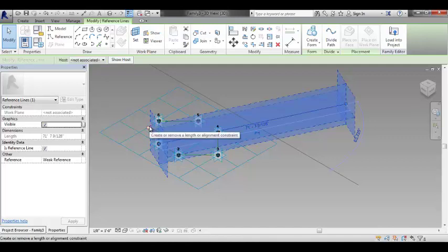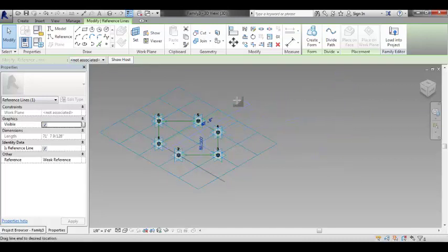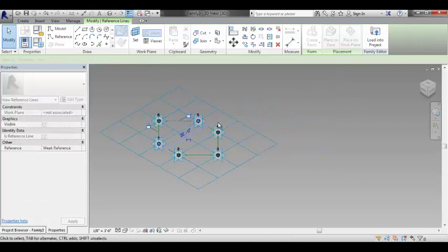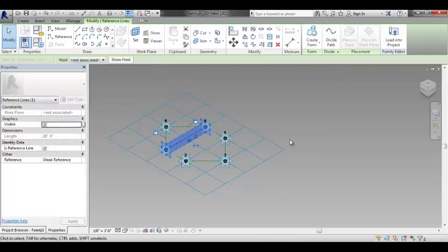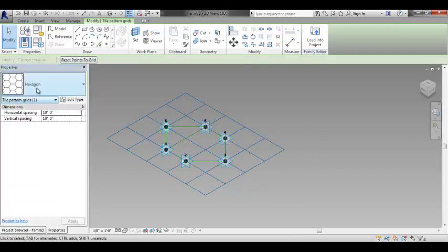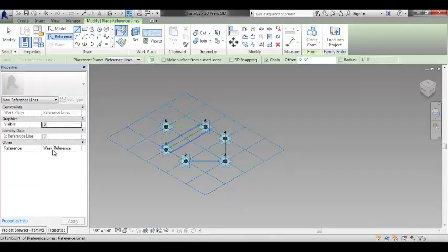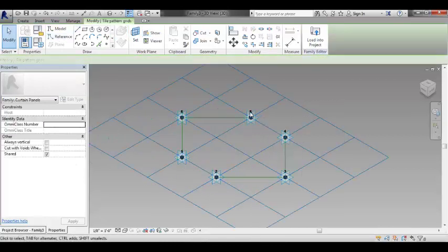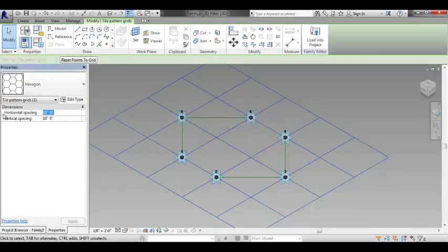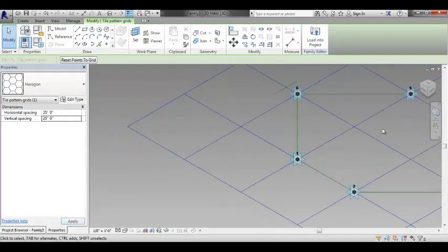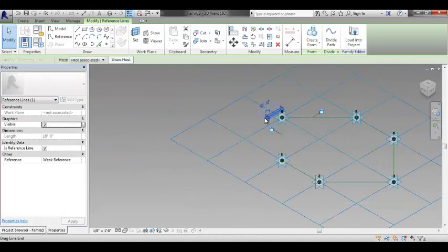Now when I drag it over, I get my little lock button. So that tells me something. It says that, hey, you're not locking to this. So I want to make sure I click on lock. Click there and I'll click lock. So now that I've explicitly told it to be locked to that, I should be able to flex my grid and it should stay. And it still didn't do it.